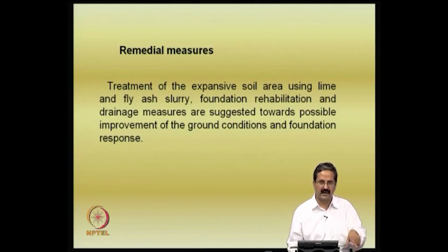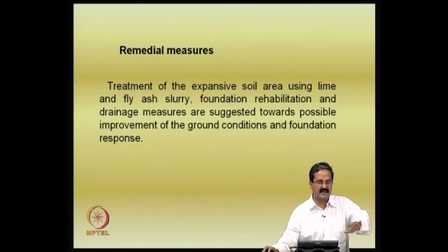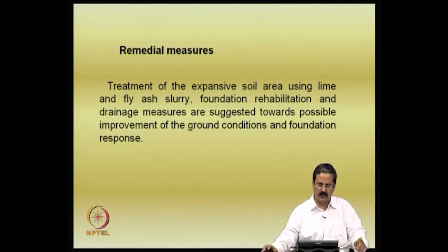If you pump under the existing foundation, actually the first thing is that we have to rehabilitate the foundation. Foundation rehabilitation is very important. If something is tilting, remove some amount of soil from somewhere, and see that it comes back to the original condition. There are so many electrical poles in the area, about 40 to 50. You have to go to the foundation and measure the actual movement. You have already measured the movement, and you remove some soil and make a structural adjustment of the foundation itself.